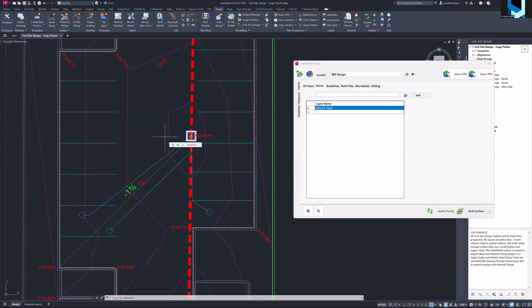Or alternatively, you'd have to put in a string in there, maybe some sort of grading to represent that low point or something like that. But yeah, if you're modifying just the surface, you're only going to change the surface, not the subgrade that comes from the model. Indeed. I was careful not to touch on subgrade just yet. I think that's now we've kind of covered off.